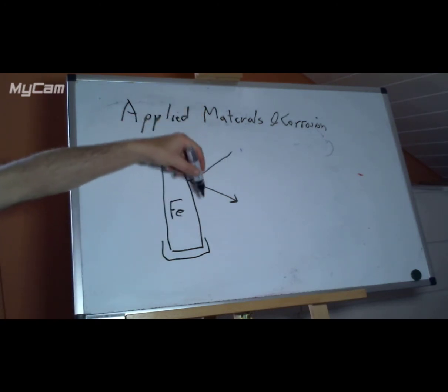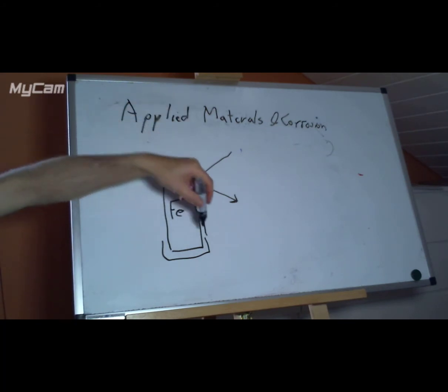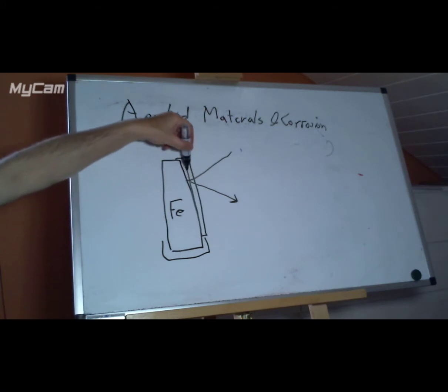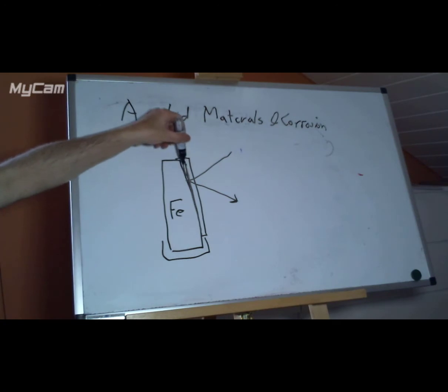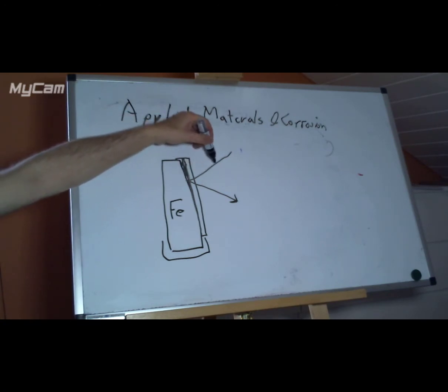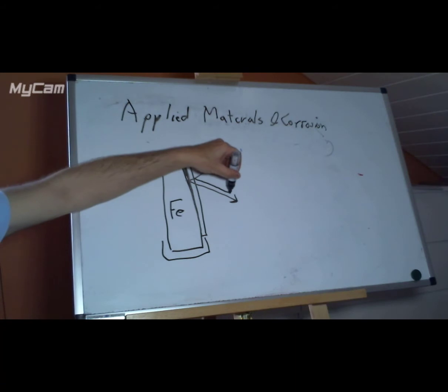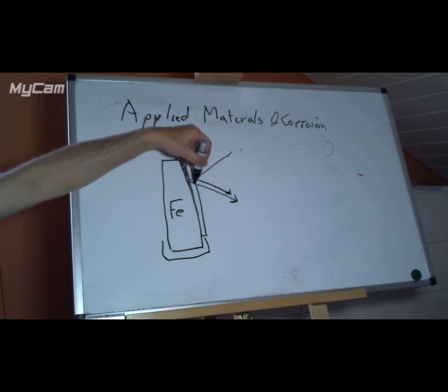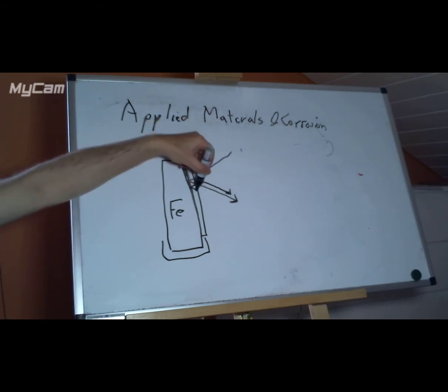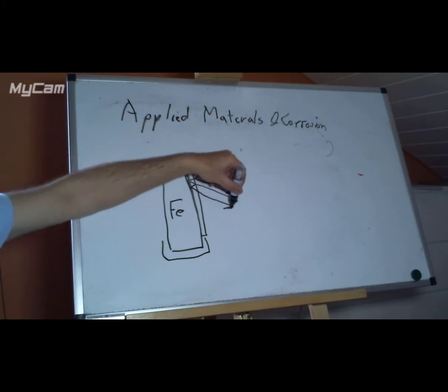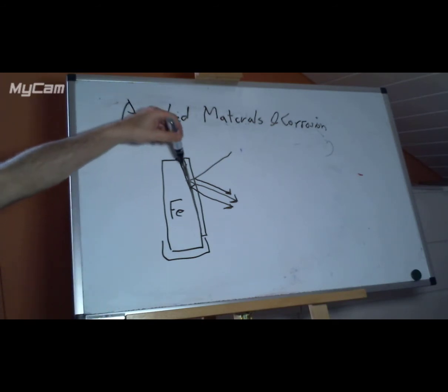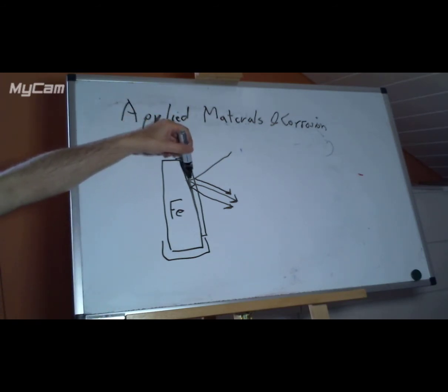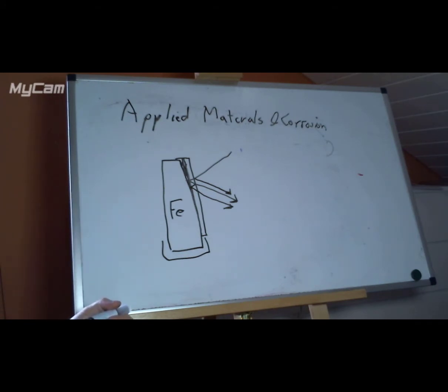Let's imagine it initially as a simple oxide layer. So we can imagine some kind of oxide on the surface, and then we will end up with a normal, relatively understandable physics phenomenon: the beam that reflects off the top of the oxide layer and the beam that reflects off the bottom of the oxide layer, and also the beam that reflects doubly, but that one's very weak, will all come out parallel to each other if the top and the bottom of the oxide layer are parallel, which means that the thickness is constant.